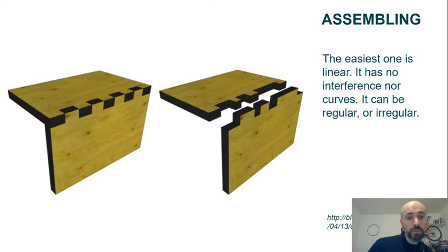The connection could be perpendicular or not, could be symmetrical or not. The angle you get to optimize the overlap of the cuts is always perpendicular. There are ways to get different angles, we'll get there, but in general keep in mind that the best and easier way to glue things together is to have them perpendicular.